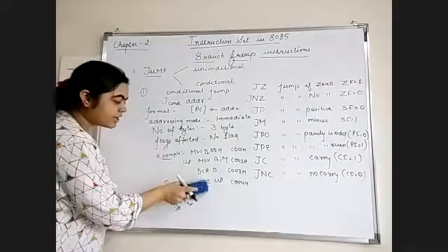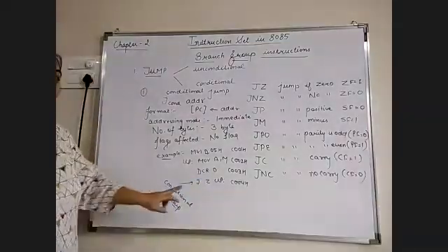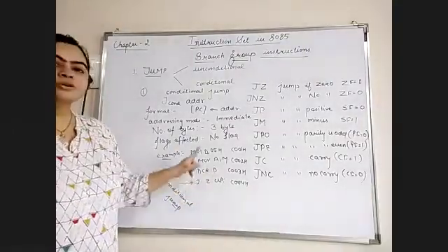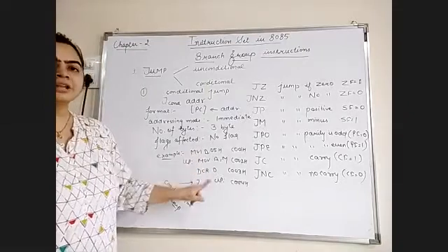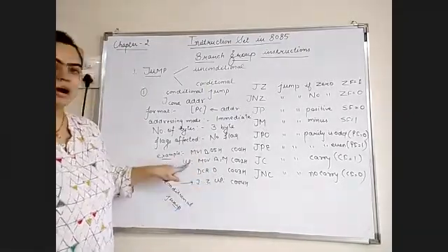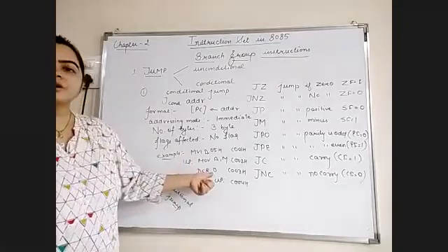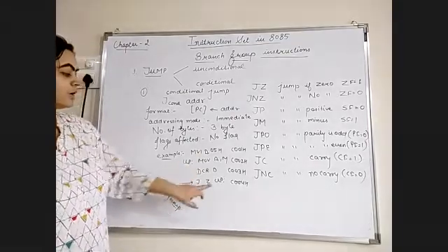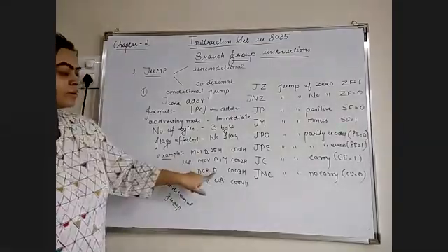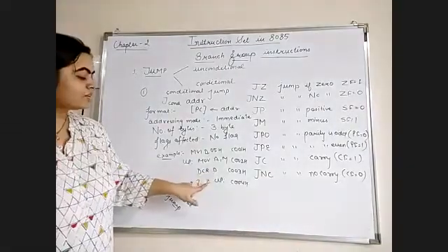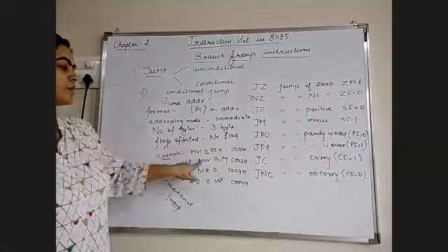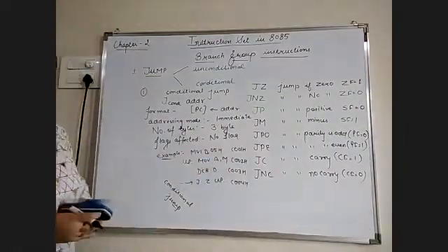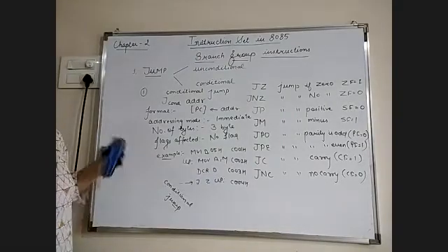And if I write JZ here, this instruction will only work when D has value 0. When D has value 4, 3, 2 or 1, this instruction won't go to UP, because D has a non-zero value. So it will not jump to UP. Only when D has value 0 will the microprocessor jump to memory location C002H. We can do the program and then you will get a better idea about conditional statements.